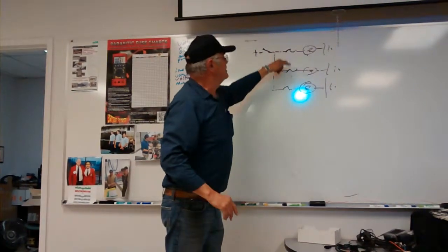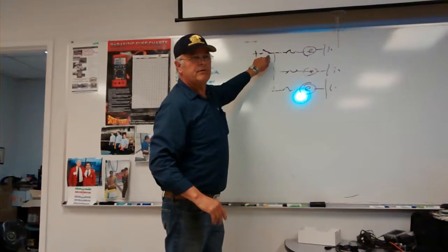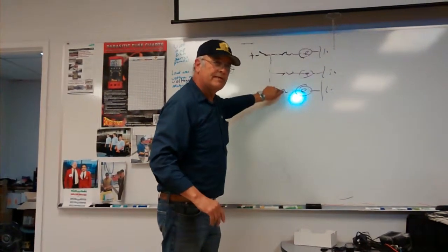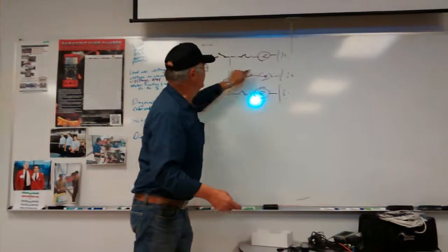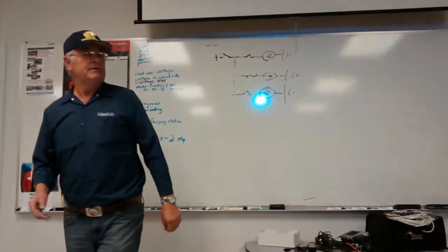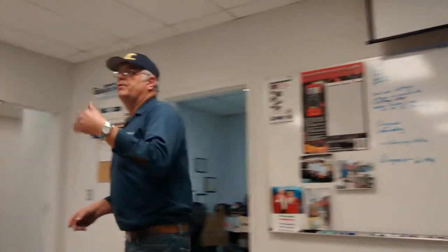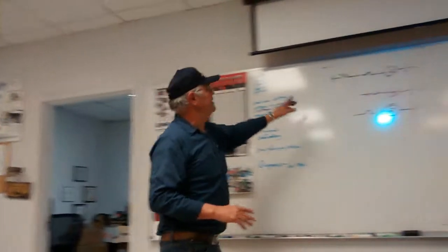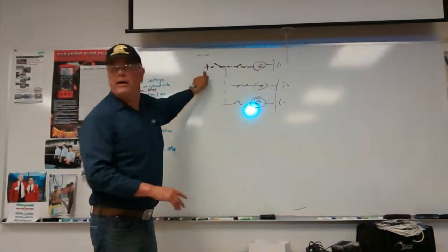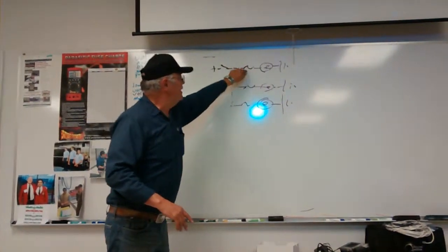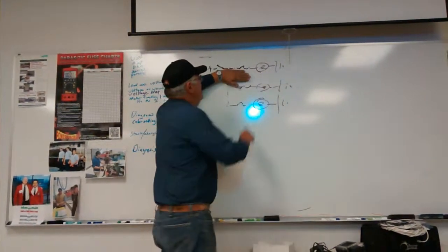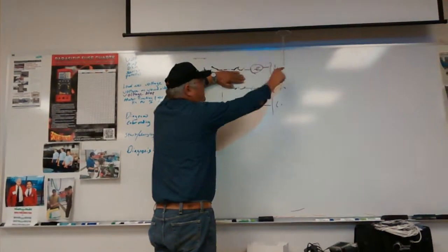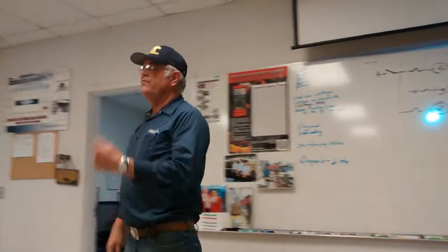So I take 3 series circuits, give them one power source. That means that they're operating side by side or parallel through a series part of the circuit. But each one of these is an independent series circuit. So when we're doing diagnostics, we can break it down and see, is it something that affects all of them? It's back here. If it's only one of them, it's that branch. And if we get to that branch, now we can break it down, and our diagnosis for a series circuit is only for that line.